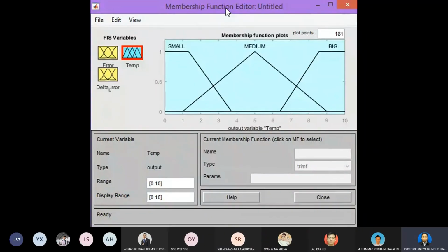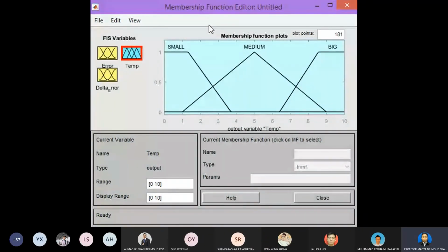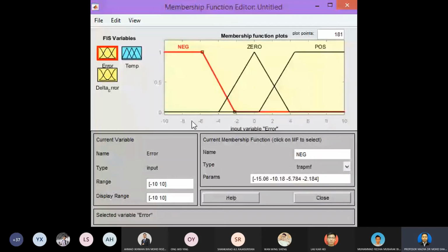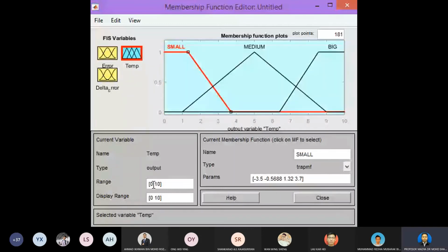Alright, so on the fuzzy logic, how to tune. We have a lot of techniques that I mentioned to you, but no specific techniques. The first technique we can adjust is the range, the range for the input and output. For example, maybe I change it to -10 to 10. Try one by one.